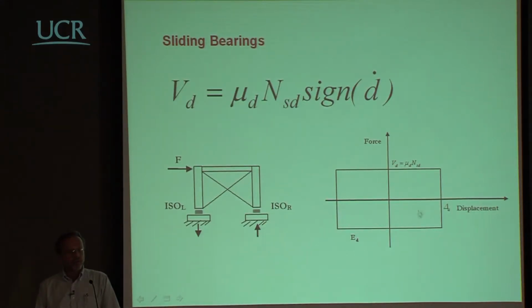Now, if you look at something like this, what you will note is that you have a very large energy dissipation capacity here. If you think in terms of equivalent viscous damping, and you try to do an equivalent calculation using the relation area divided by 2 pi, whatever was written in these 2 days, you will find out that the equivalent damping of something like this is 64%.